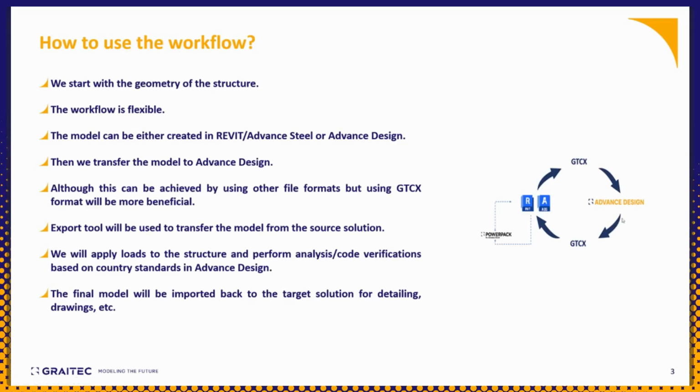and through GTCX, again, send it back inside Revit or Advanced Steel. Through this workflow, all of the loads, even if you have defined some loads in Revit, will also be transferred inside Advanced Design. And talking back from Advanced Design inside Revit, all of the internal forces in your beams, columns, and slabs, as well as, if you have done a concrete design, all of the required rebar areas will be transferred inside Revit.